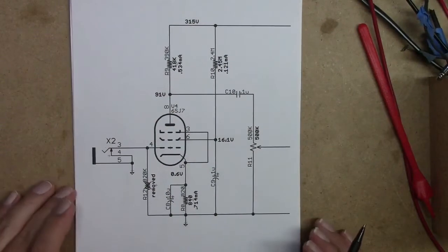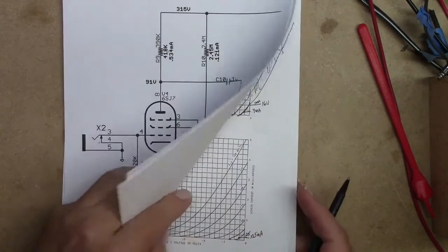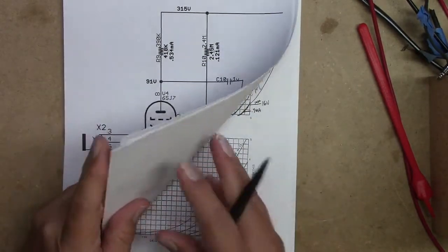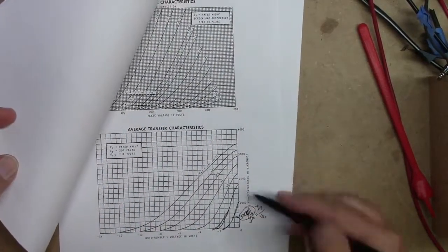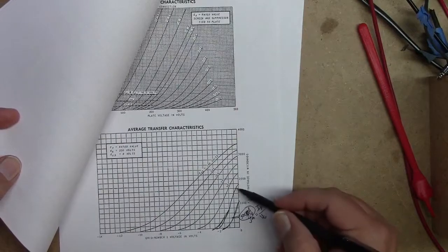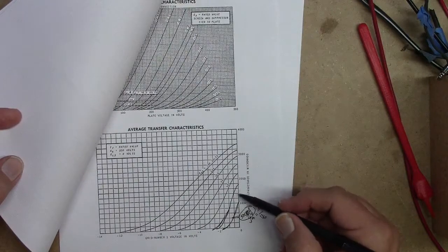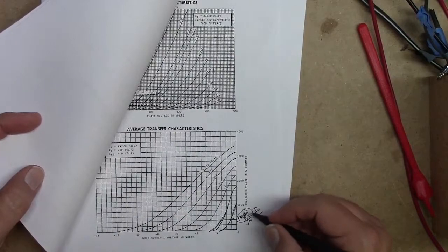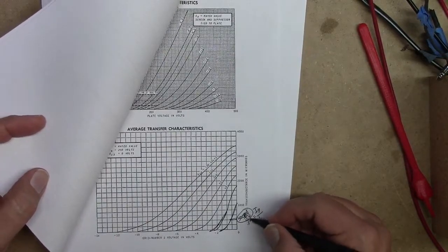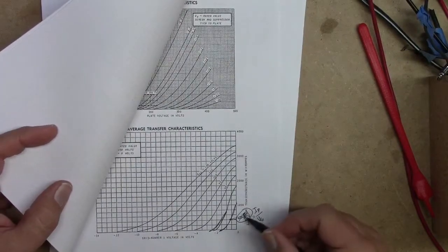All right, one last thing to look at is the G sub M, our calculated value, or our estimated value for G sub M. We got that off of this one graph out of the data sheet by extrapolating. This is for the transconductance in micromhos. We drew in a 25 volt line for the screen voltage, and then I estimated where the 16 volt was, and I came up with 500 microamps per volt, or 500 micromhos. All right, so let's go see if we get this number.